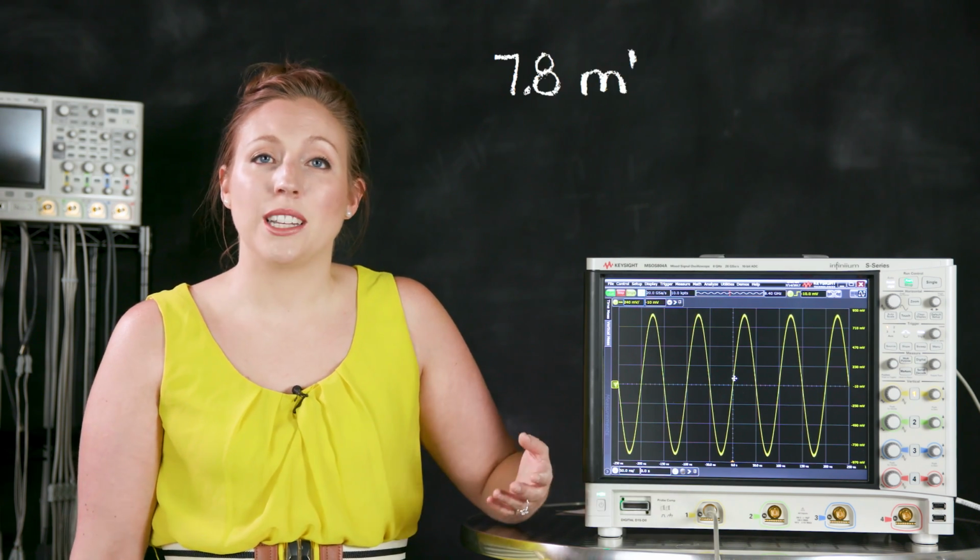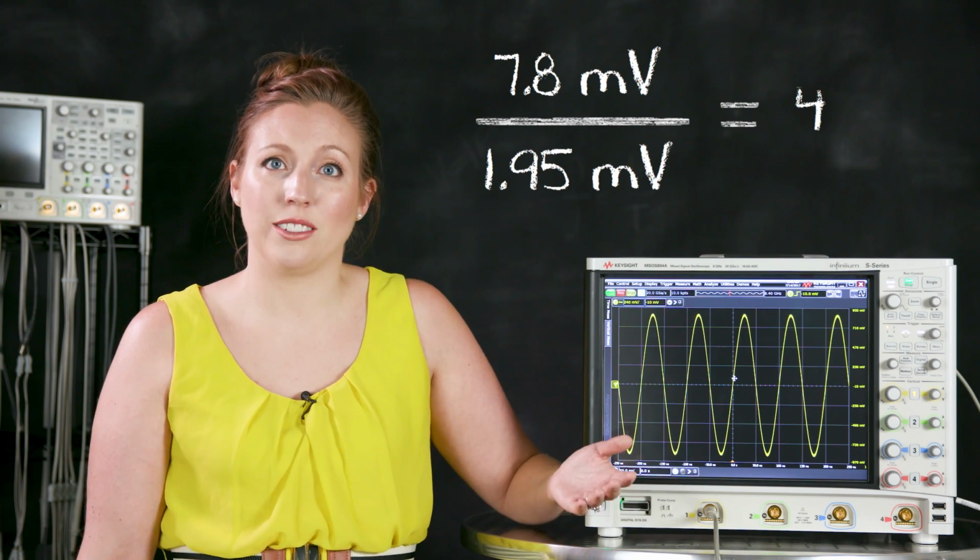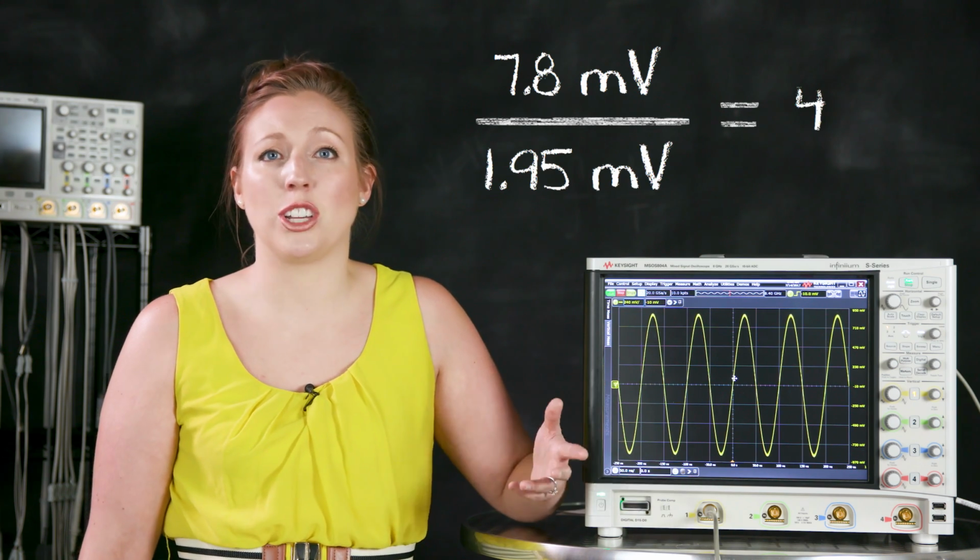As we can see in the math that we just went through, 2 additional bits can potentially give you 4 times the resolution. I say potentially 4 times more resolution because there's a lot more to consider. For starters, there's no such thing as an ideal analog to digital converter. This means that just the process of quantizing that signal can induce noise and jitter. The better the ADC, the less noise will be injected. Therefore, if you want to know the applicable specs of the ADC, you want to look for the effective bits of the ADC to account for any noise added in by the analog to digital conversion. That will get you one step closer to understanding the quality of measurements made by the oscilloscope.